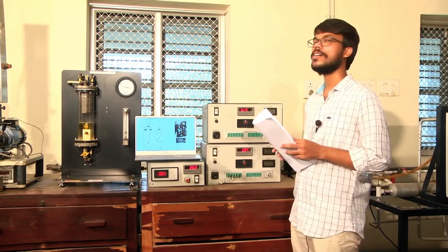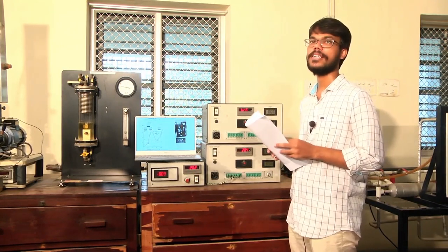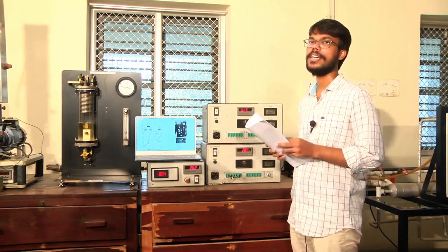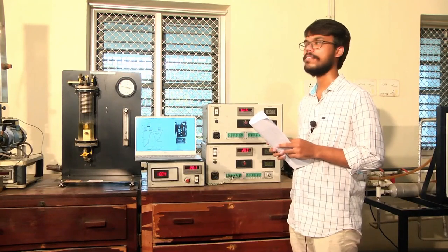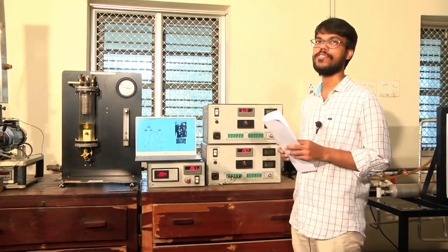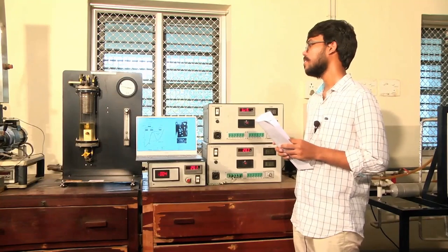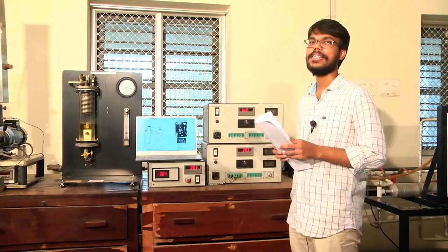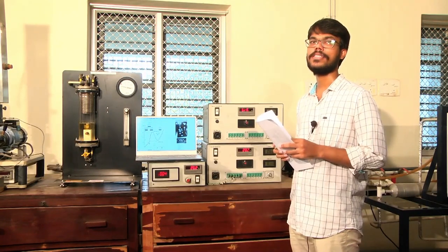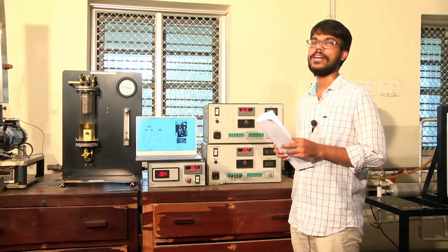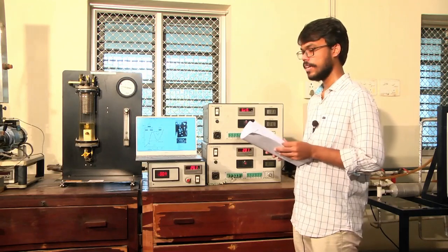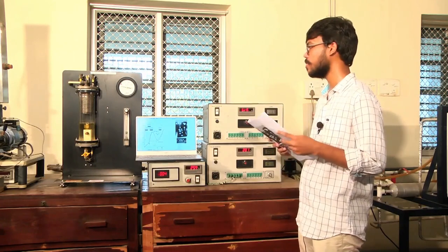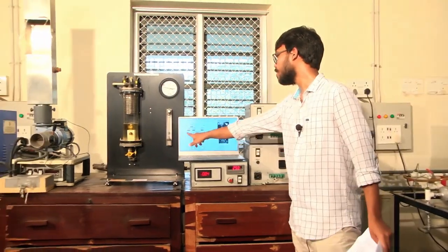The pioneering work on boiling was done by Nukiyama in 1934. He conducted pool boiling experiments using nichrome and platinum wires immersed in water, and he could observe 4 different regimes. The first regime is natural convection boiling, the second is nucleate boiling, the third is transition boiling, and the fourth regime is the film boiling regime. And he also plotted the pool boiling curve, which is shown in your manual. You can see the boiling curve here.